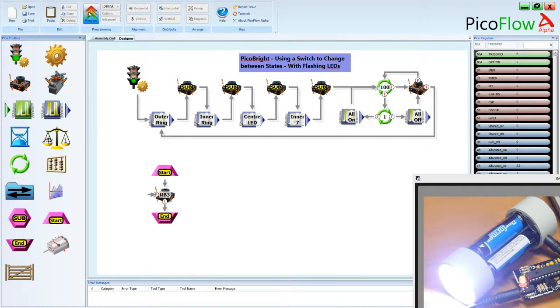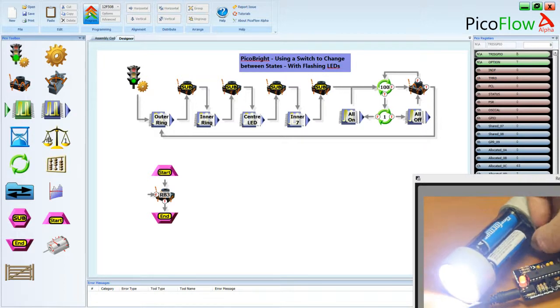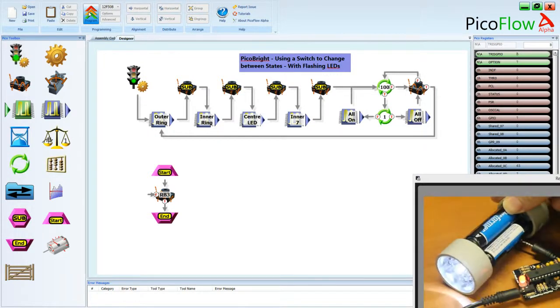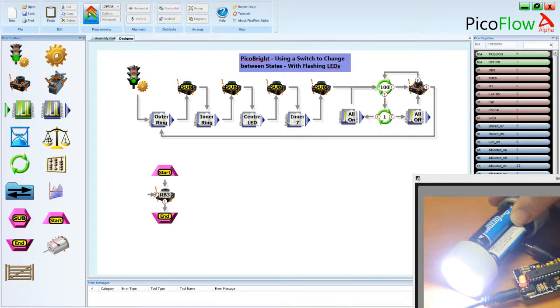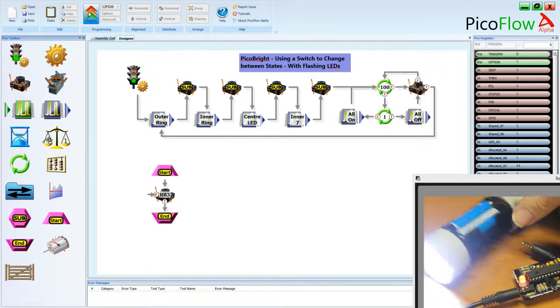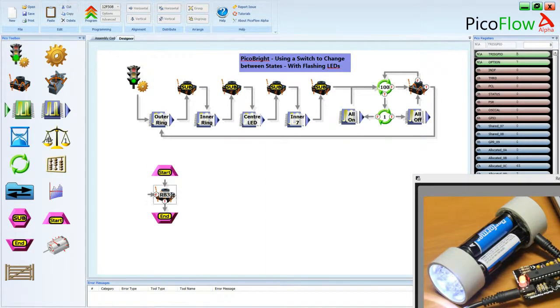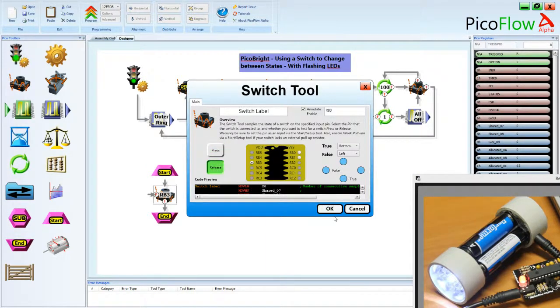This should work a lot better for us. And we'll unplug the programming socket. So center LED, 7 LEDs in a 7. Oh, didn't that flicker? Okay, so we're back to outer ring. So inner ring, center, inner, and oh, did that flicker again? Okay, so the problem is that I think we've got a press routine maybe on this one when it should be on release.